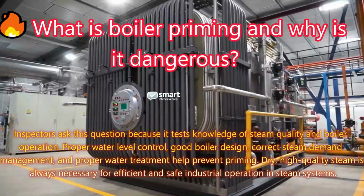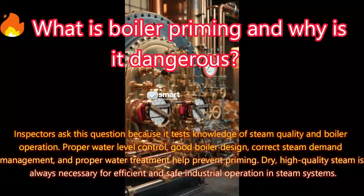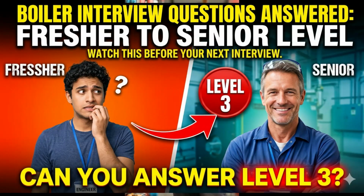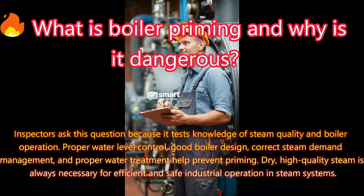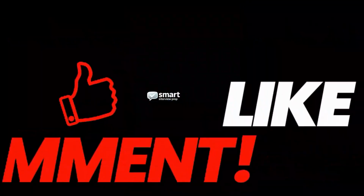Inspectors ask this question because it tests knowledge of steam quality and boiler operation. Proper water level control, good boiler design, correct steam demand management, and proper water treatment help prevent priming. Dry, high-quality steam is always necessary for efficient and safe industrial operation in steam systems.